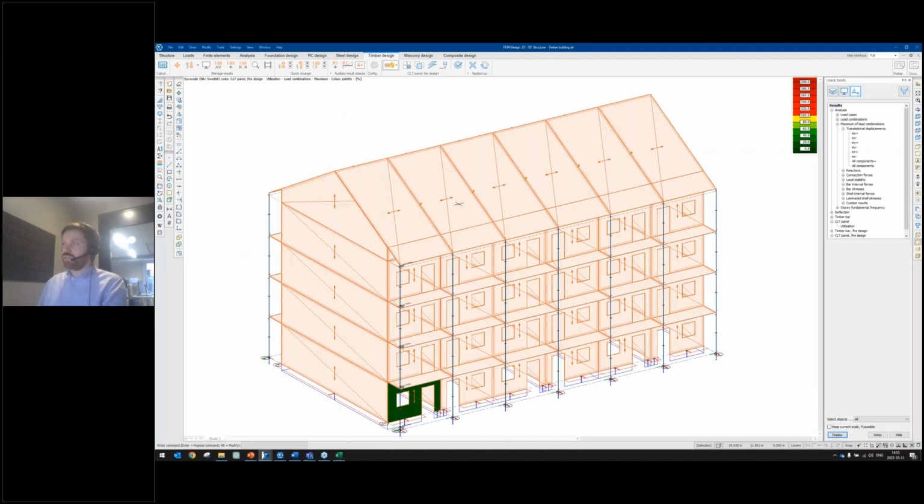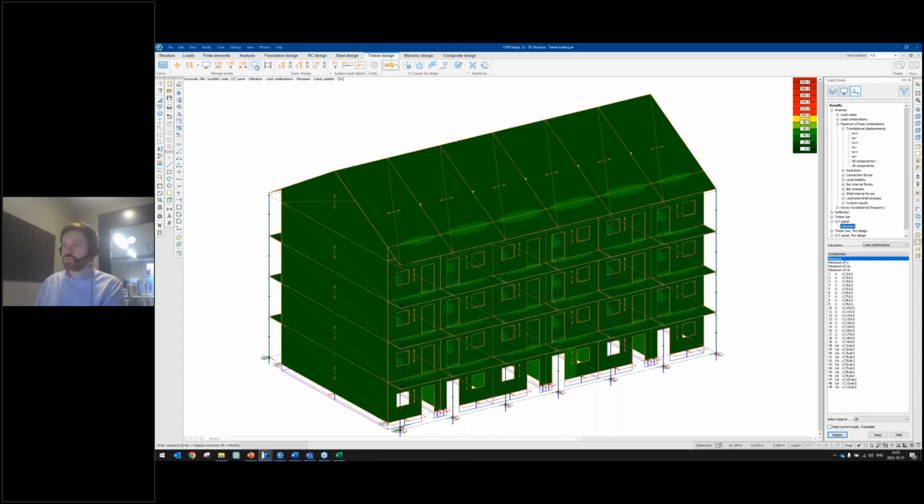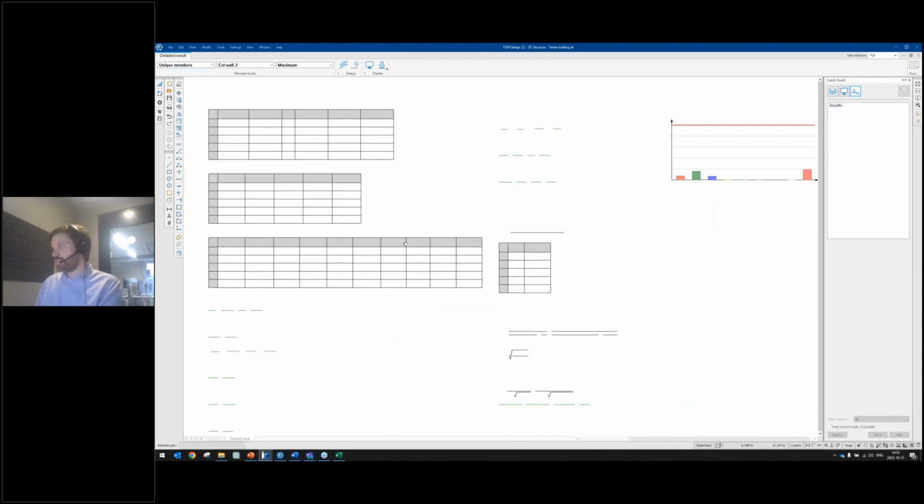That's not the case if I do the documentation inside the software using the documentation module. And here we have an option. If you want to do a quick and easy documentation, you can just use the shortcut Control-D. You can take any view and just paste that into the documentation. It can be a view of a 3D view. It can also be a formula, like maybe I want these formulas in the documentation.